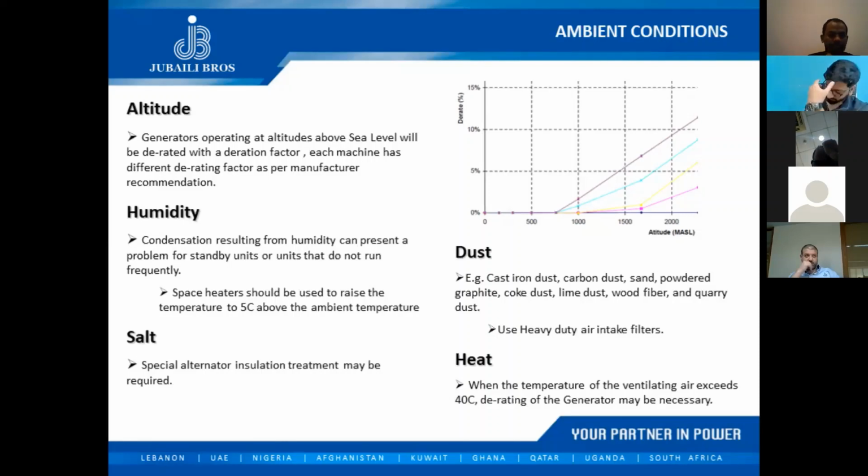Same idea related to altitude. With altitude, air is less dense, thus it's less efficient in cooling down our machine. That's why both the engine and the alternator would experience derating with the increase in ambient temperature and with the increase in altitude.